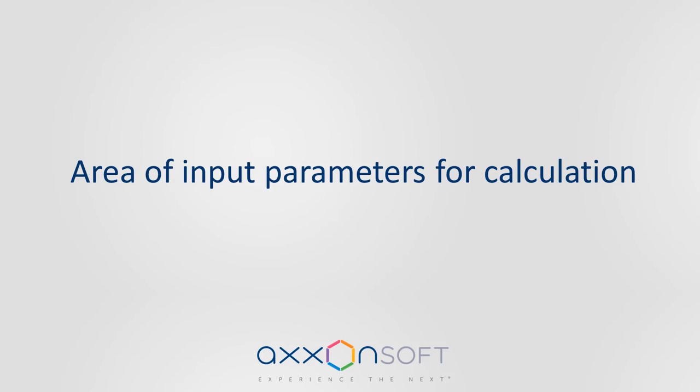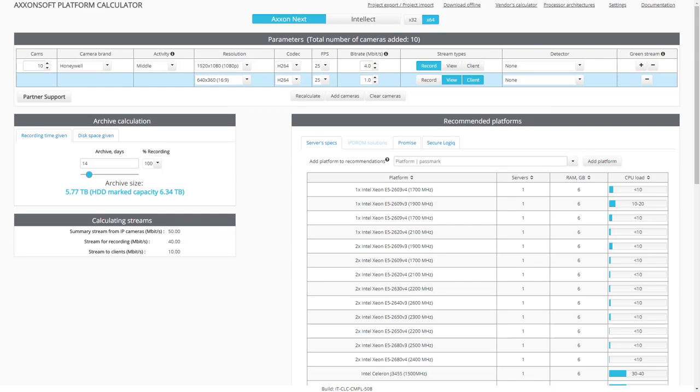Area of Input Parameters for Calculation. The main parameters of the video surveillance system that affect the calculation are: software used, Axxon Next or Intellect; system type, 32-bit or 64-bit; number and model of cameras; activity in the camera's view; resolution, codec and frame rate of the video streams; number and purpose of the video streams; and using video analytics. Next, we will discuss each of these parameters in detail.